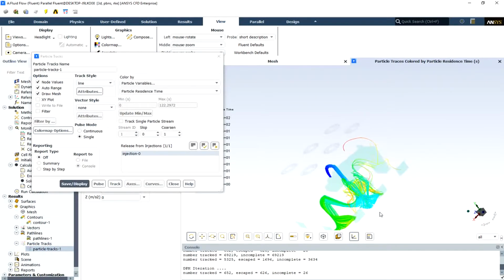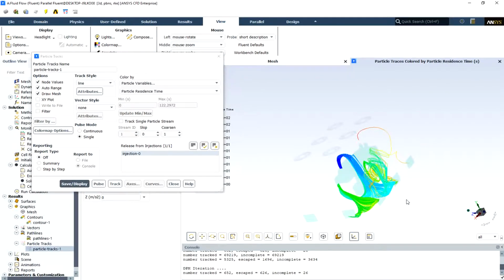As we can see in this three-dimensional particle tracking, the particles and flow exit from the patient's mouth and enter the clean room environment, and then exit from the 3 closest outlets. By extracting this result, we can see that the ventilation performance is acceptable, and also we know in which direction the particles are going.